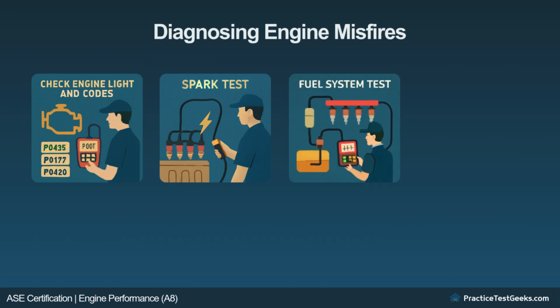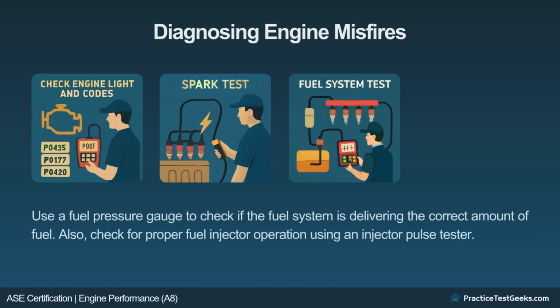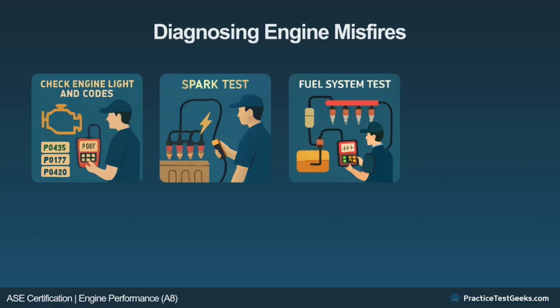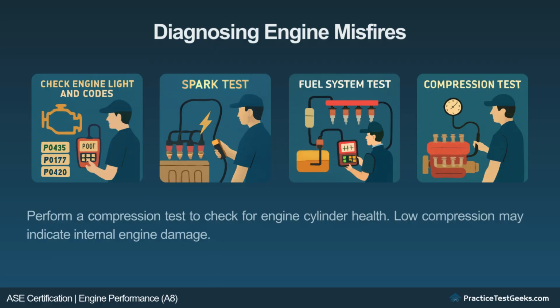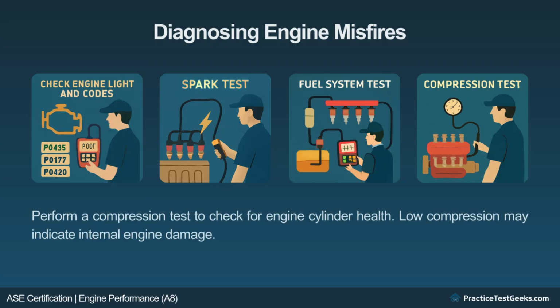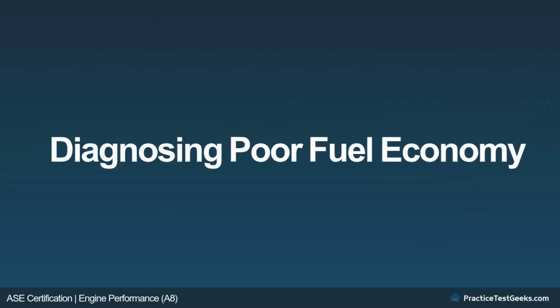Fuel system test. Use a fuel pressure gauge to check if the fuel system is delivering the correct amount of fuel. Also, check for proper fuel injector operation using an injector pulse tester. Compression test. Perform a compression test to check for engine cylinder health. Low compression may indicate internal engine damage.